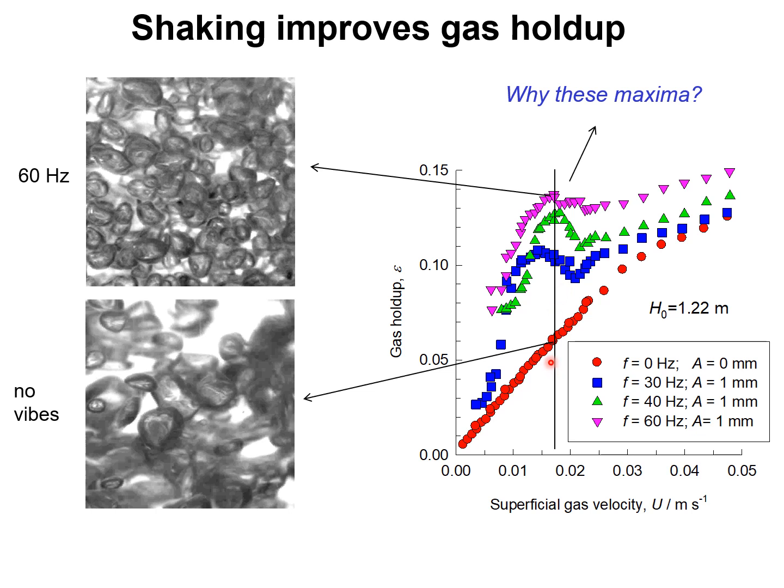We see for any given superficial gas velocity, there is a significant improvement in the gas holdup due to low frequency vibrations. But you also note that there are maxima in the gas holdup when operated at the frequencies of 30, 40, and 60.